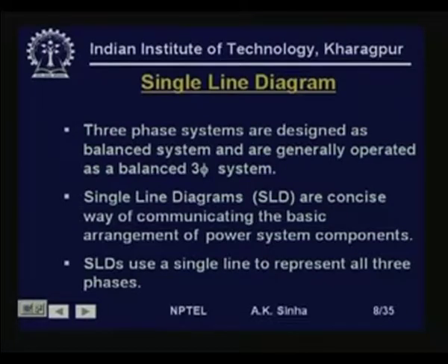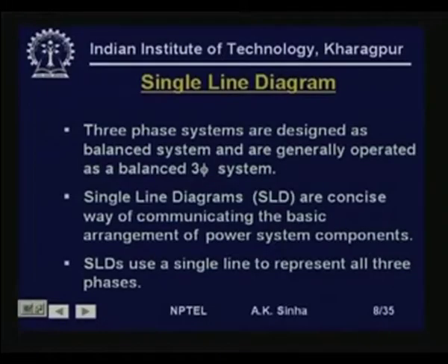That is, what we need in case of representing graphically the power system network is to see the basic interconnections of various components, so that we know what is connected where and how. So, this is what we try to do using the single line diagram. Now, single line diagrams, which are also called SLDs, use a single line to represent all the 3 phases.